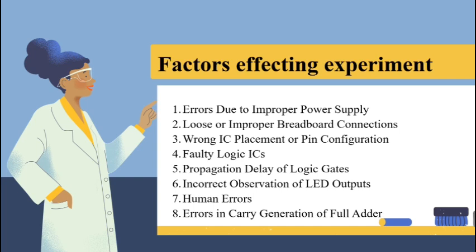The common problems are a broken breadboard strip, wrong row connections, and adjacent rows shorted accidentally. To prevent this, double check all the wiring before powering the circuit. Use color coded wires for inputs, outputs, VCC, and ground. Test continuity if outputs are unstable.